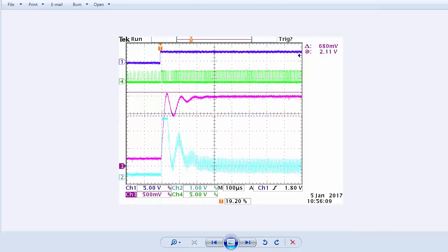The top trace is the scope trigger, the next trace is the PWM timer pulses, basically the plant input. The next trace is the buck converter output voltage, and the bottom trace is a current probe point in the evaluation kit. Each pulse represents one 5 microsecond cycle.